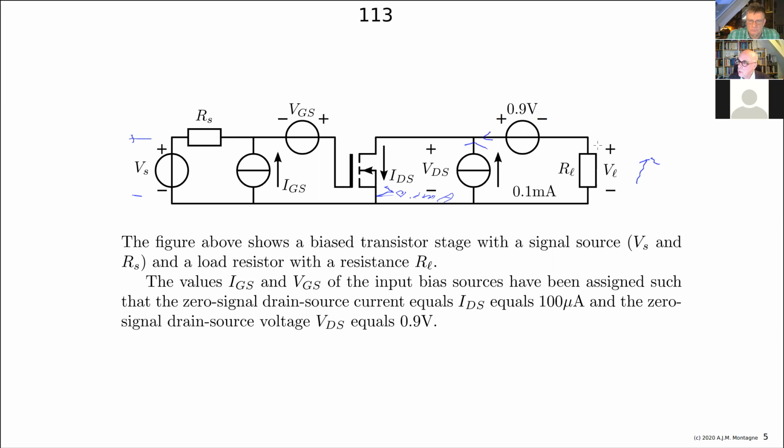Now, let's say here we see that the current is flowing. This output current is now flowing from the negative terminal to the positive terminal. So this one is definitely delivering power, this bias source. So this one and this one, well, even if you would drive a lot of positive voltage, the voltage across the MOSFET will probably never become exactly zero. It will always remain a little bit positive because there's current flowing through it, and the on resistance of the device will not become zero. It will be maybe 1 microohm, but there will always be a positive voltage.